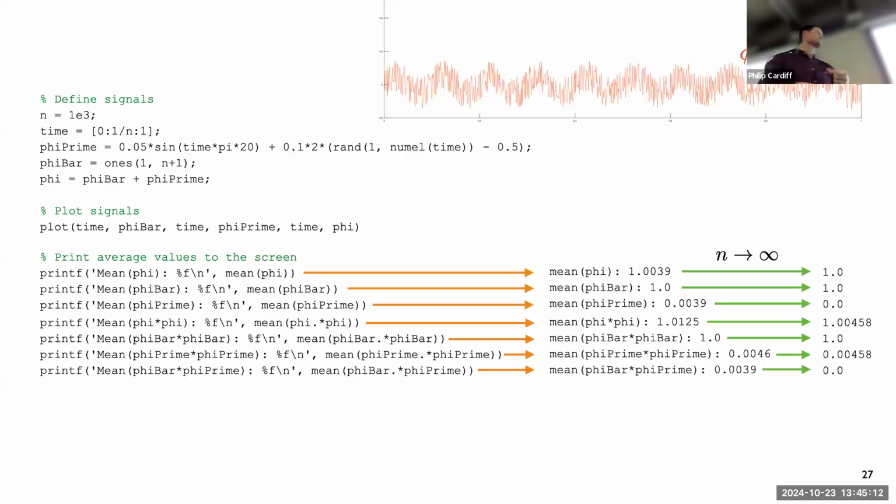The mean of that is not 0. So if I take that noise signal and multiply it by itself, that's essentially squaring the value. Sometimes they're negative, sometimes they're positive, but if I multiply by itself, that's squaring, so all those numbers have to be positive. That means I'll have noise that's always greater than 0, so the average of that is obviously going to be non-zero. It'll be the midpoint of that.